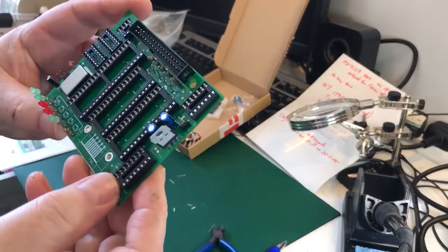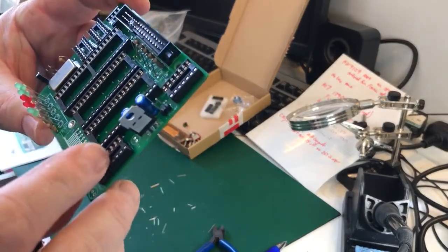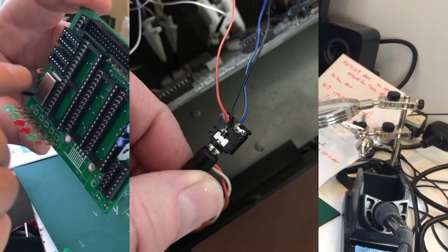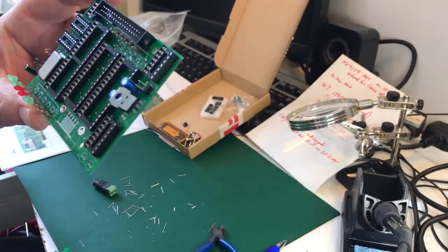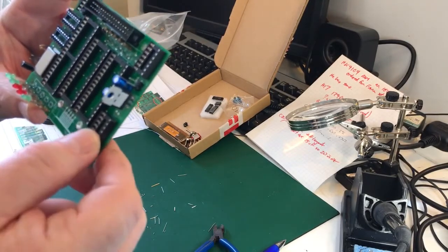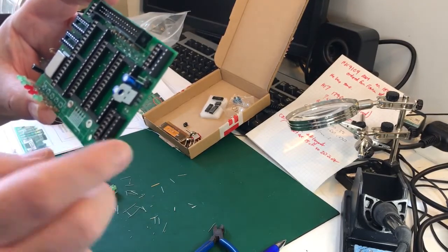That's pretty much the completed board as I'm going to do it. I'm going to make a little adapter now to stick the connectors in there, and I'll make a little reset switch on a flying lead. I'm not fitting these 4 caps, obviously, because they're for the Max 232, which I'm not going to fit, nor the header.